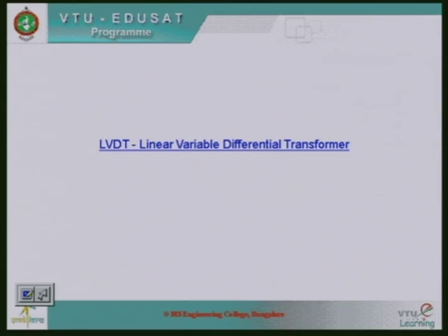Okay, now let us summarize. The summary is this. We discussed resistance temperature detectors. In a resistance temperature detector, we have taken a small wire. We know that the length of the wire is fixed and the cross section of the wire is fixed. But we all know that the resistance of the wire changes with regard to temperature. Because the resistance of the wire changes with temperature, we can use this as a transducer.